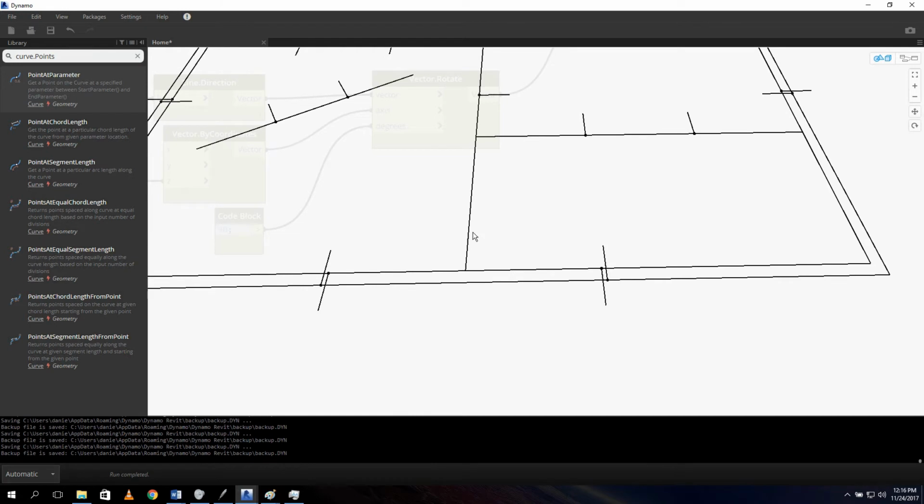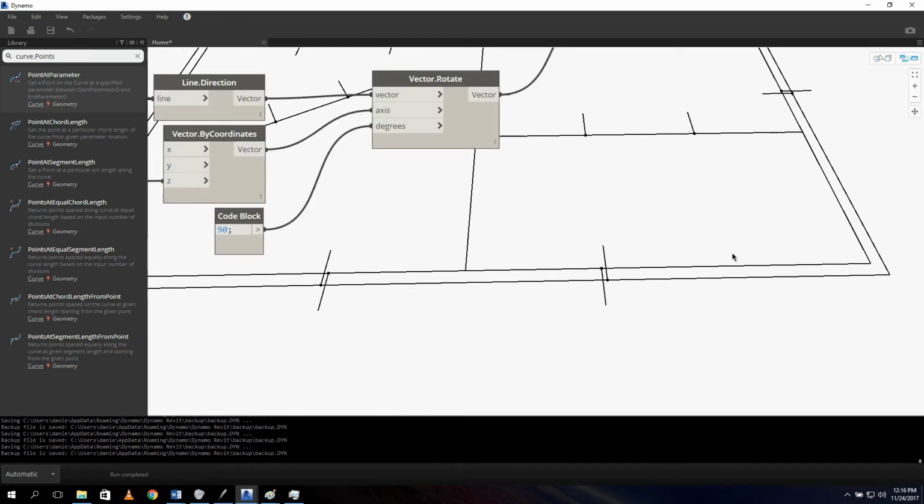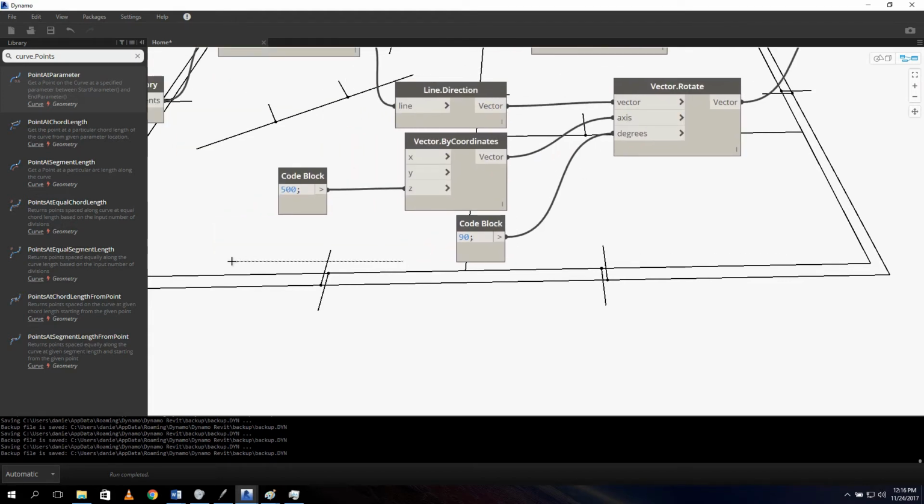We created 2 points because if the wall starts over here, for example, and ends over here, like the cursor is right now, this line will detect it, and it will say, all right, this wall and this wall need to be joined with each other. But this wall, what I'm representing right now, is not on this side. It's just going from here to here, and that's it. And then it joins this wall as well, and maybe you don't want that.